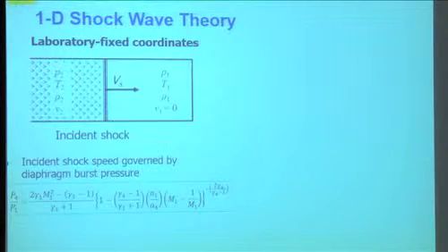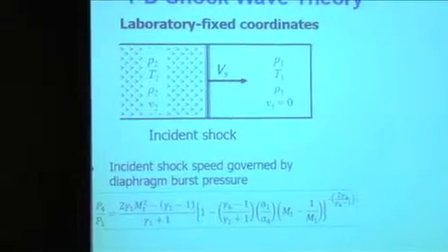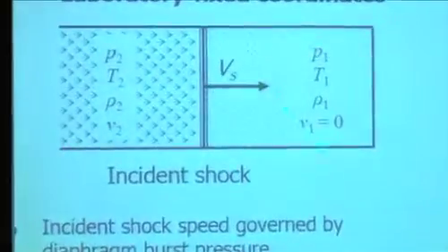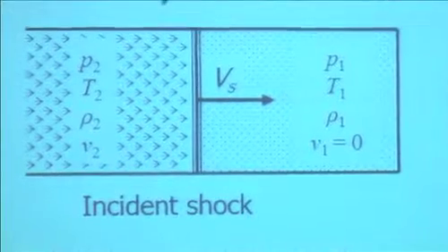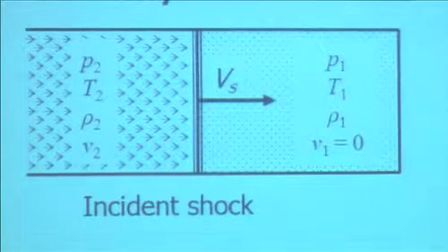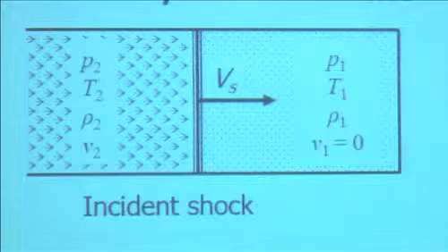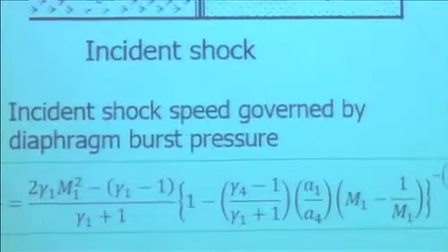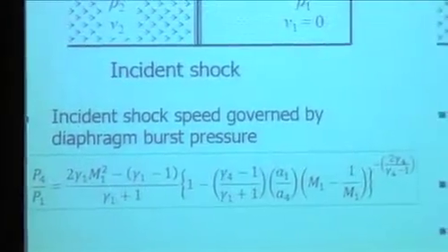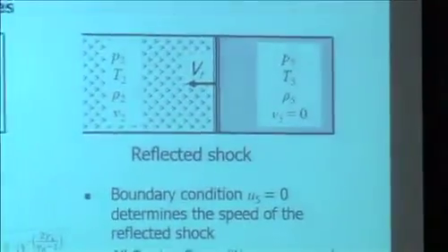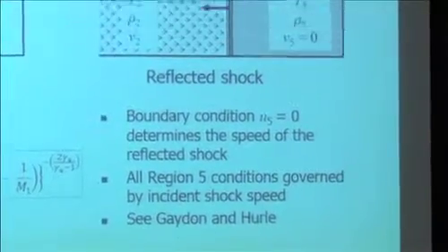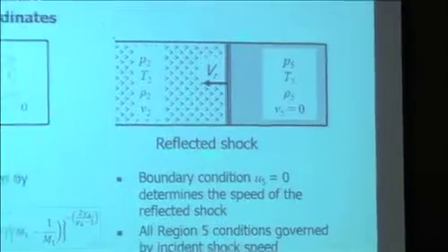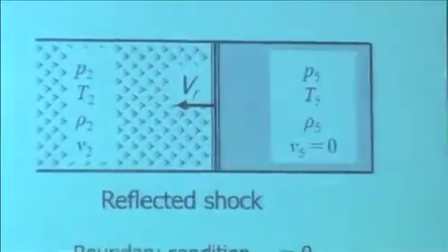The theory, maybe you've seen this, probably you've seen this. If there's a moving shock wave, and you know the conditions upstream, you can solve for the conditions in the shock. You can solve for the conditions everywhere, across the wave or even in the driver gas. You can calculate kind of everything with standard relations. You have to say something about gamma. You have to know the composition, but then you can calculate everything. So you can also calculate what happens behind this reflected wave. If you measure the speed coming in, you can calculate the conditions here quite accurately.